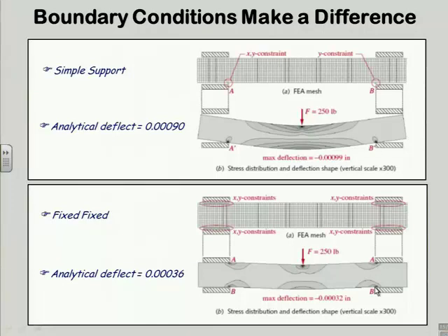And notice the stress concentrations at the end of the bearing. That is consistent with what we talked about when you have a roller running over something, and where the roller stops, you get a stress concentration, right? Same concept here.